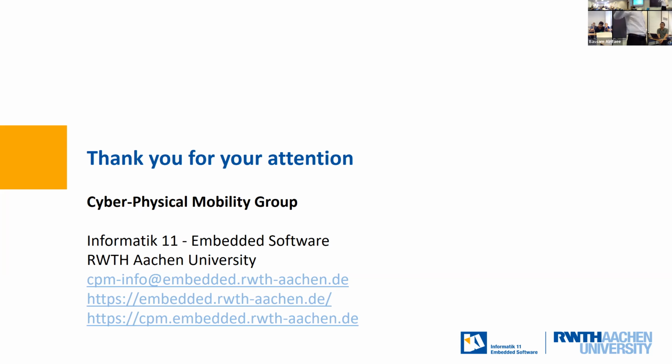the real-world project, the Unica Ideal project. We have there 5 high-level computers, 4 for the sensors. On each corner, we have sensors and computers to compute the image stream, the laser beam stream, the radar streams, and so on. And in the middle of the architecture, of course, we have a high-level computer which computes the high-level trajectory planning and stuff like this.